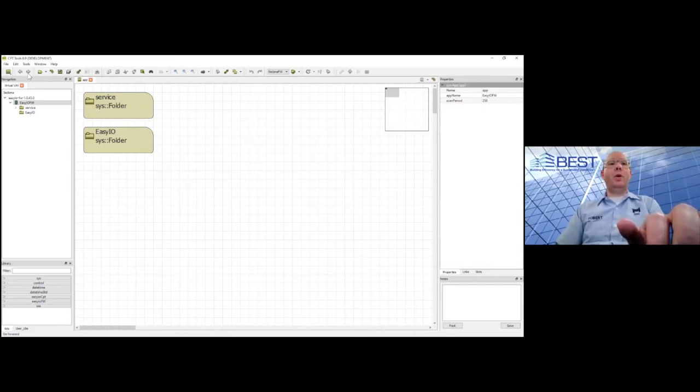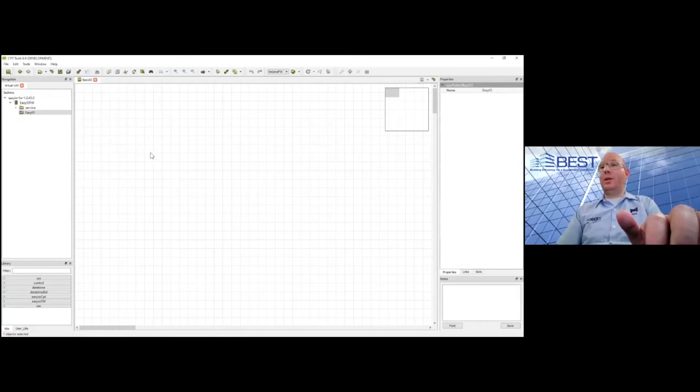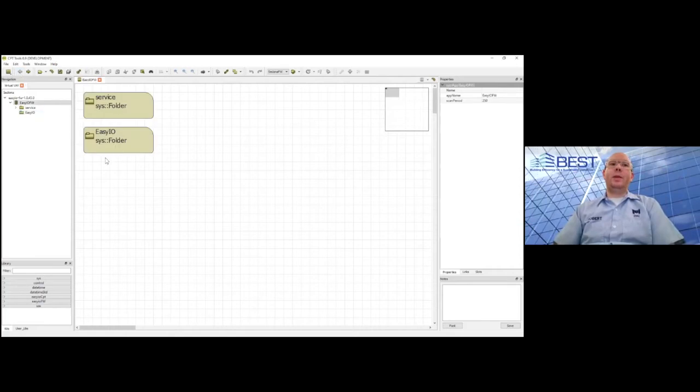The last one that I want to point out is the left and right arrows up here in the upper left-hand corner, and specifically the back button. This works just like a web page forward and backwards. There will be times, I guarantee everybody will do it at some point, when you'll be looking at an object and you'll accidentally double click on the object and suddenly everything you were working on disappears. Don't worry, you just dove into the object like it was a folder. Hit the back button once, and everything should be back to normal. Okay.